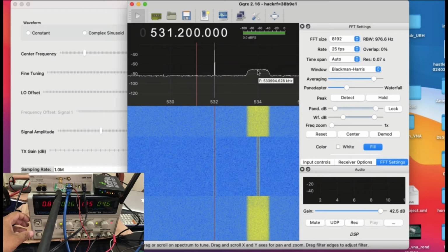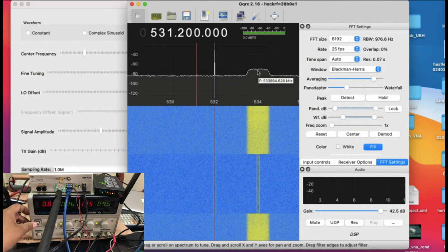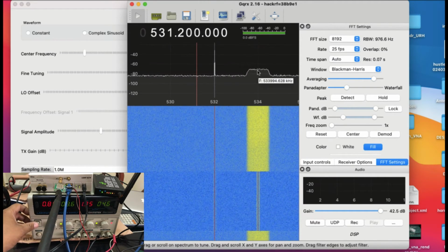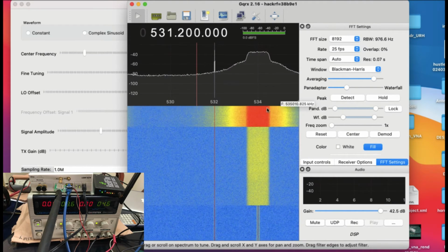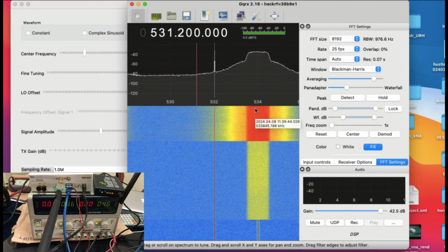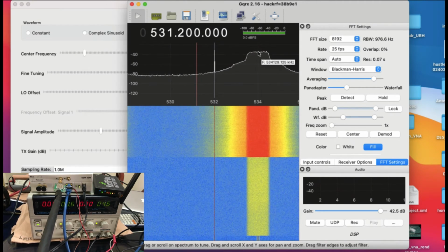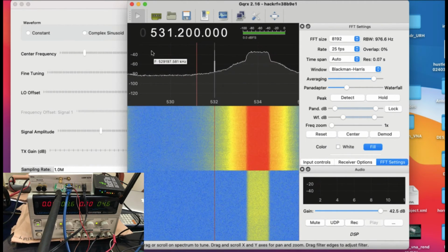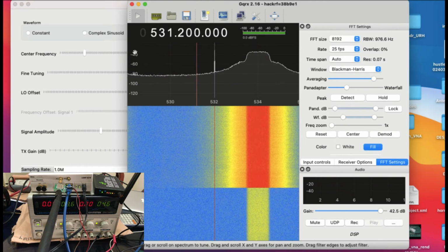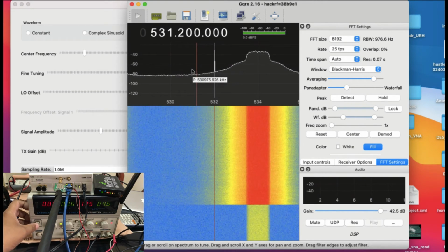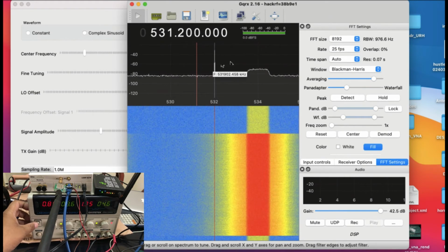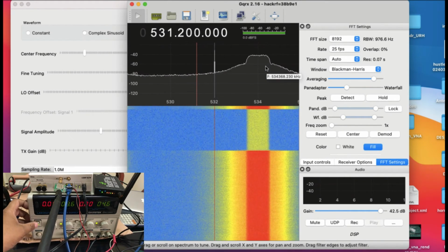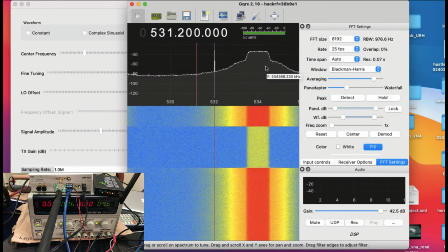Now when I turn on my amplification, let's turn on the amplifier biasing, and boom. So as it was green, and now all of a sudden you're getting an entire spectrum that is somewhere around -40, I would say even -30 dB. Your signal was somewhere around right here at -80, -70, and you're getting about a 20 dB jump when you're using an amplifier like this.